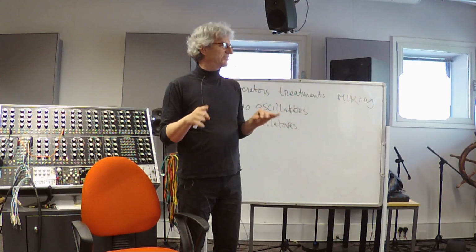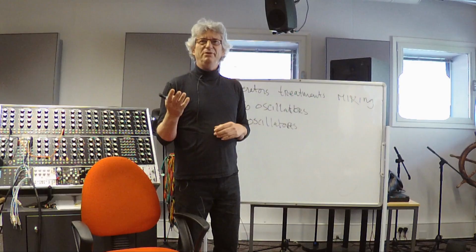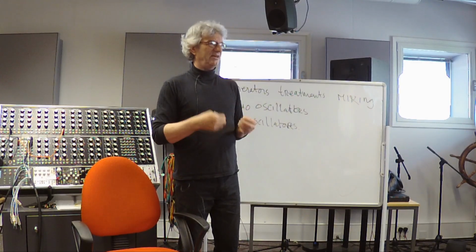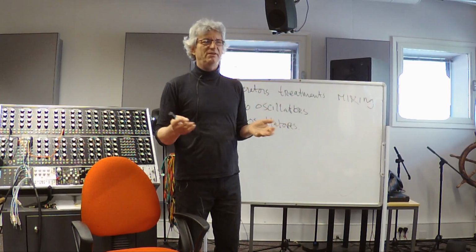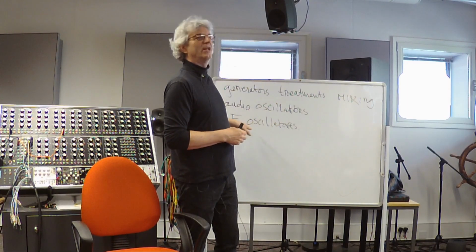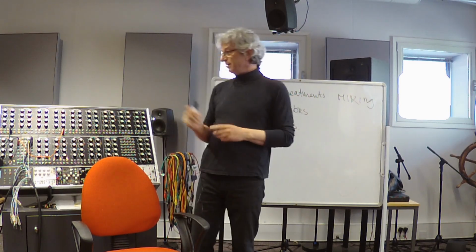So for me, I don't really make a lot of distinction between LFOs and audio oscillators, except that the audio oscillators have this, because they're analog and they're slightly sensitive to environmental things like temperature and humidity. They have this extra special circuitry to stabilize their pitch for temperature, etc., which are not on the modulation oscillators, although they can also go into the pitch range. That means that if you want to have exact tunings, you need to use the audio oscillators. The others you can also tune exactly, but if the temperature changes or the humidity changes, they may drift a bit.